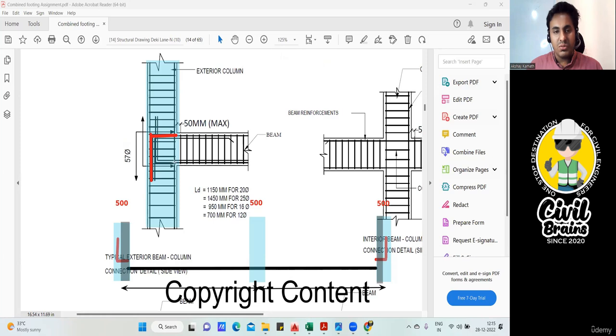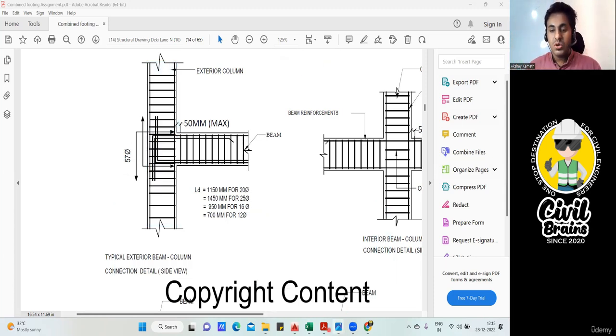Similarly, your bottom bar will come, from here to the top. How much is it? It is 57 times the diameter of the bar. This is clearly mentioned here. So we'll take the development length as 57 times the diameter of the bar. This much is clear? Good. So I'll go back to that.